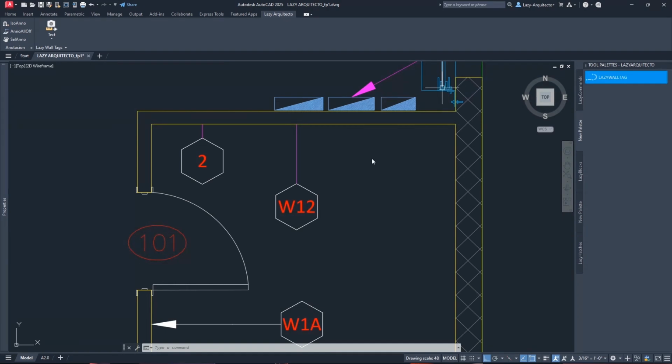So that's why I like to share my whole process and not just a beautiful code where you didn't know how I arrived at that point of the code. Anyway, my AutoCAD is frozen a little bit. Let's give it a couple of seconds. But we're very close there, guys. We're gonna try to add this system variable ATTREQ, and we're gonna set it to 0 to wrap up this awesome tool for wall tags.